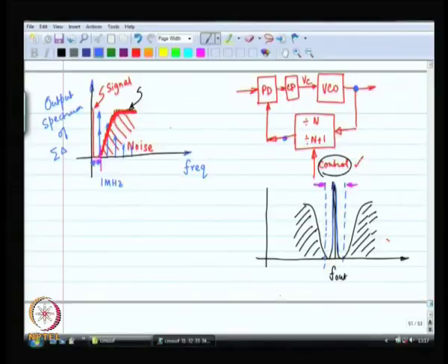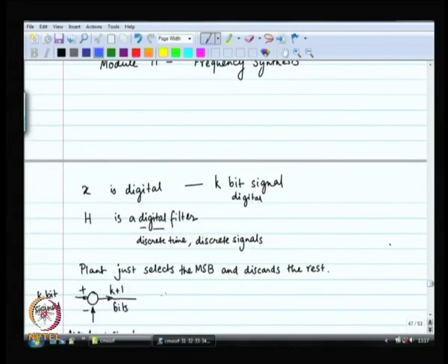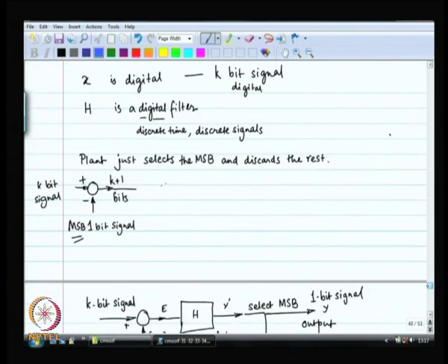We pulled up sigma delta modulators from our A to D converter book, and we modified it a little bit, because we are not really doing analog to digital conversion. We already have a digital number, we are going to create a 1-bit digital number whose average represents the original digital number.